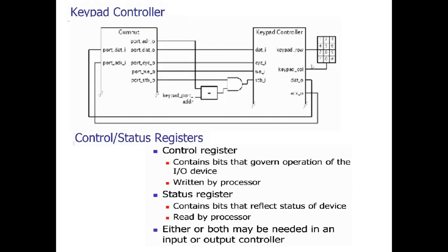When the embedded processor needs to access the input or output register, it provides the address of the required register, and we decode the address to select the register, enabling only the reading and writing of that register. So we can use address decoding circuits connected to the processor to identify whether memory or IO registers are being accessed, and we can enable the memory chips or the appropriate register as we require.